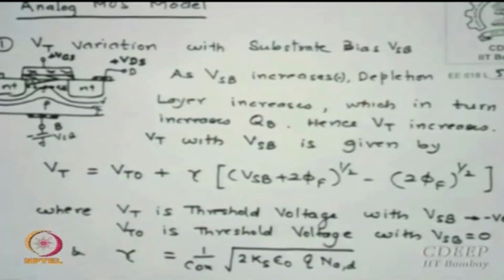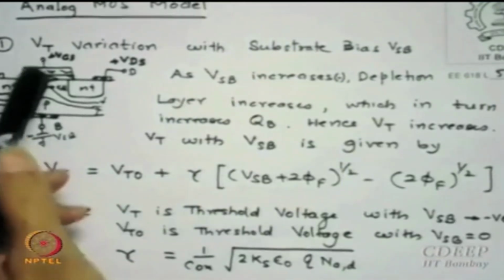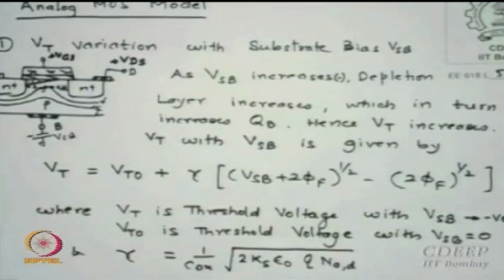is increasing, we know the expression which we have written for Vt, which has a term Qv by Cox, phi ms, 2 phi f, Qox by Cox, minus Qb by Cox. That time the bulk charges were essentially because of the VGS, that is what we said, Ex is very large and whatever depletion is occurring is essentially because of VGS. But now you have created an additional source for depletion charge, which means now Vt will become higher, because already there is a depletion. So you have to first remove that to get into an inversion layer, is that clear?